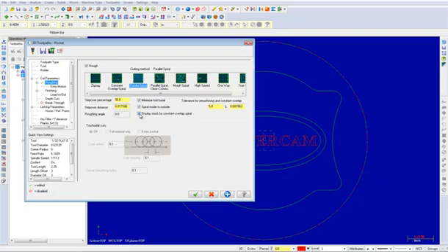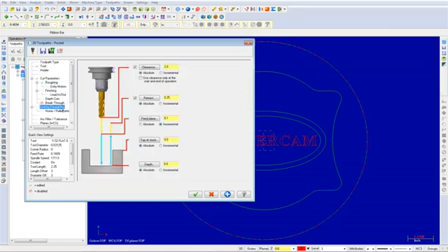The finishing, lead in, lead out, and depth cuts parameters are the same as the previous toolpath, therefore, we do not need to view them. That being said, select the linking parameters. Change the depth to an absolute value of -0.125. The rest of your parameters should appear as shown. You can now select the OK button to generate the toolpath.